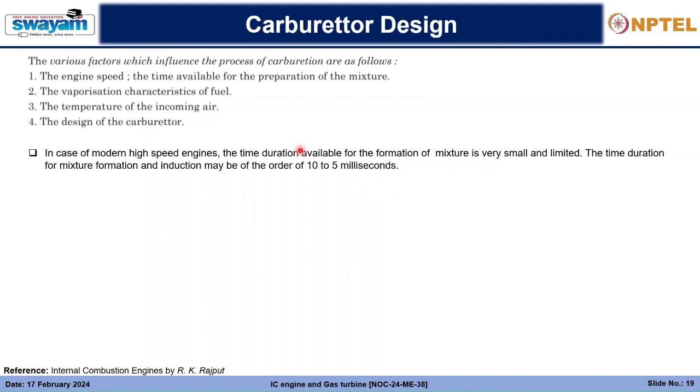Hence it's a two-stroke engine, and the time duration available for the formation of the mixture is very small, because the faster it revolves, the faster the whole stroke completes. If the stroke is completed in a very small time, you get even less time to vaporize the whole mixture, and then the mixture coming inside the cylinder is burned in the very next stroke. So you must understand the time duration of the formation of mixture is very small and limited.